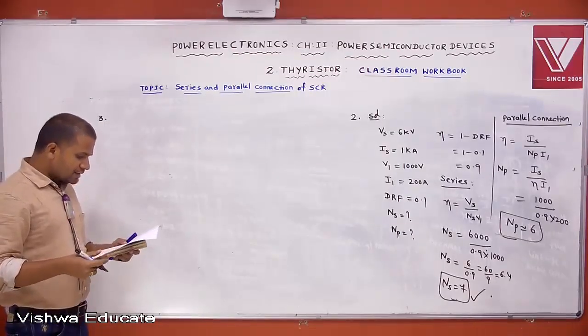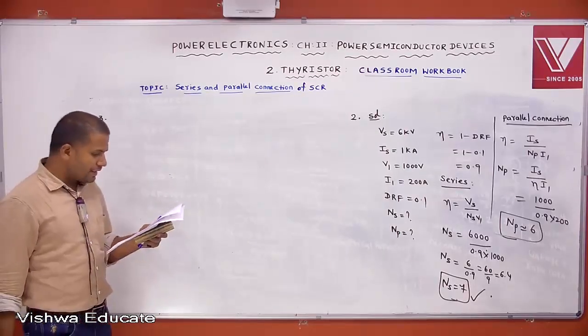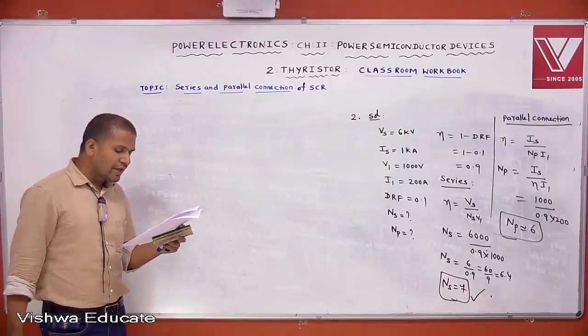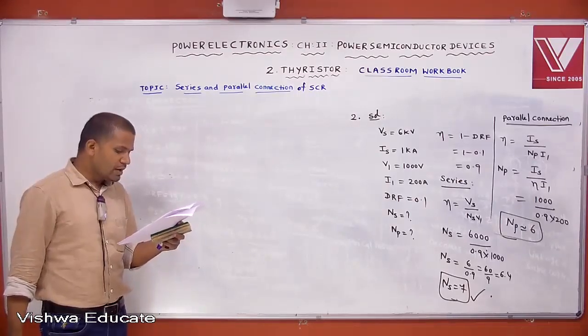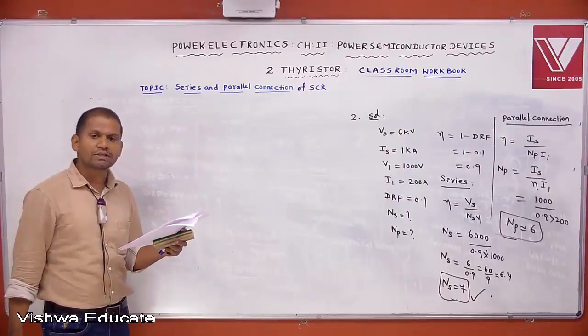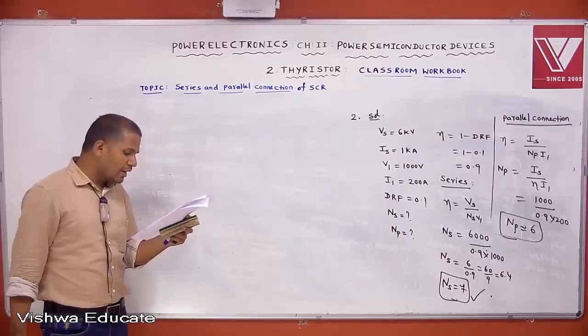A thyristor string is made up of a number of SCRs connected in series and parallel. The string has voltage and current ratings of 11 kV and 4 kiloamperes respectively. The voltage and current ratings of available SCRs are 1800 volts and 1000 amperes. For a string efficiency of 90%, calculate: